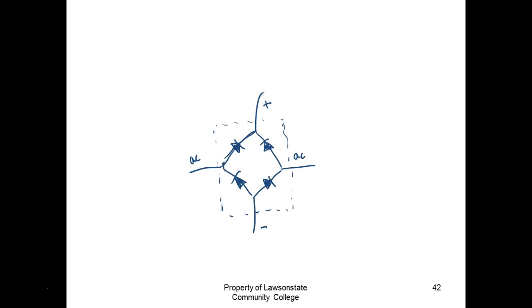Now, y'all hear what we have to put our meter on the AC side. So what I would do is I would come over here and I would take my meter. It doesn't make any difference. But if I put my plus over here on my meter, and I put my minus up here, then what diode would I be checking? I'd be checking this diode right here.